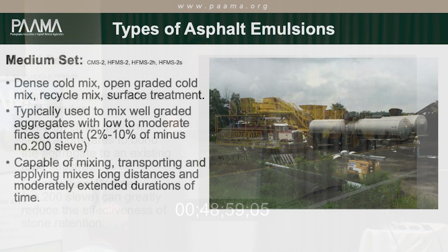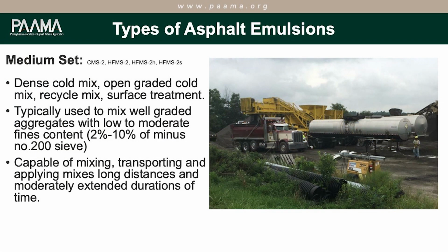We have medium sets used for dense cold mixes, open graded cold mixes, recycle mixes, surface treatments. Medium sets are a little bit more forgiving for dirtier aggregate, but obviously you're going to sacrifice your set time. So a medium set being a slower emulsion will give the emulsion time to penetrate that dust and stick to the stone.